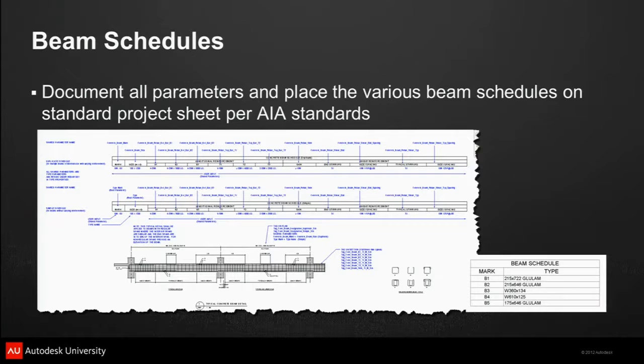So we have a couple. Actually, the second one is redundant. It's still in the template. We had to recreate a duplicate schedule to compensate for beams that have the same size but different reinforcing. So the template is forever evolving. We've got a typical detail linked to it.